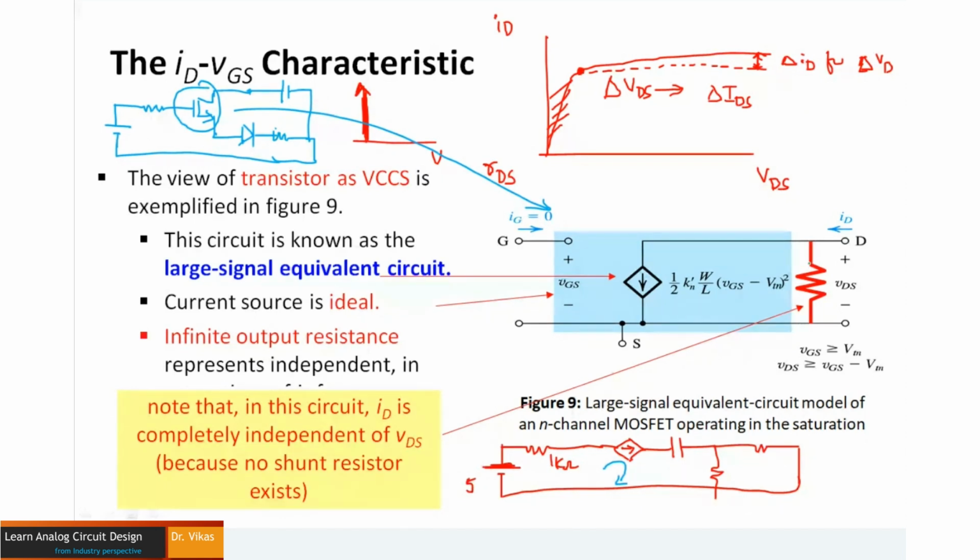And there is a small resistance observed in the saturation region, that is, a small incremental current is also observed. I'm talking about the practical scenario. So if I consider this as my gate terminal, this as my drain terminal, and this as my source terminal, between drain and source, where did you observe the channel?